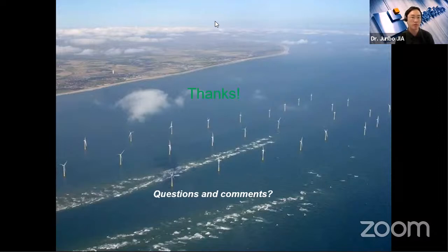And also, if you don't want to install those spiral plates, because they can cause increased wind drag or some hydrodynamic problems due to the increased wind loading or the drag wave loading, you can actually add some damper. What I just mentioned is this dynamic absorber. There are also many different applications. You can add those dynamic absorbers purely to reduce the vortex-induced resonance vibration on your structure. You can see many examples in the engineering world, and there are also some research articles describing that. So I hope those questions are answered properly, or if you have more questions.